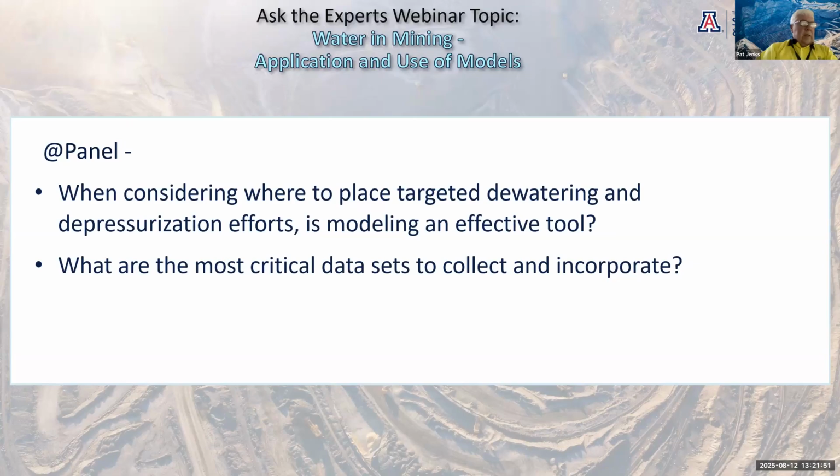Yeah, I just echo what Jim said earlier and advocate for the performance-based approach. Don't jump right into the model. Let's get some monitoring and some performance tools out there to assess how a test well or a test pumping well is going to perform.